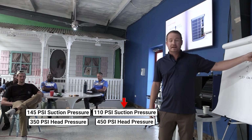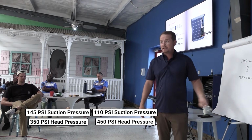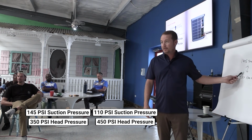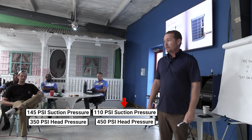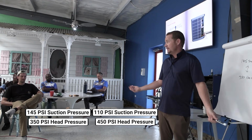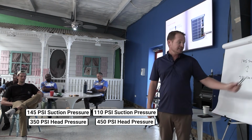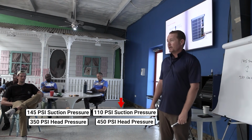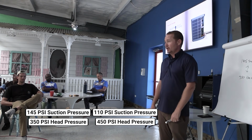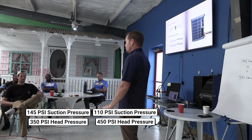Why? Because there's a bigger difference between this and this, versus this and this. Which compressor has to work harder? The one on the right. Which system is going to move more BTUs? This one. Which one's going to move less? This one, right? Which compressor is going to run hotter? The one on the right. Which compressor is going to last longer? The one on the left, right? Really, really simple.